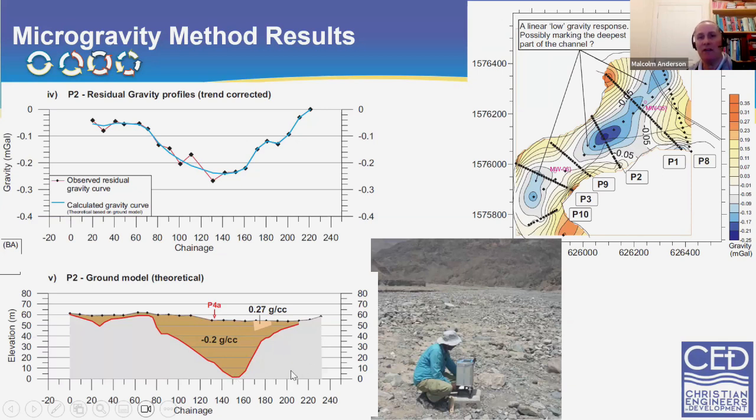Unfortunately, it turned out that the groundwater level was very close to the bottom of this unit, because effectively the sands and gravels were acting as a French drain and draining the bedrock and transferring it down the wadi. So although it looked dry here, there's quite a lot of flow, but it's in that bottom 2 to 3 meters. Nonetheless, the gravity method, as you can see, is a very useful method for determining the cover rocks and the depth of the cover rocks in a river valley.